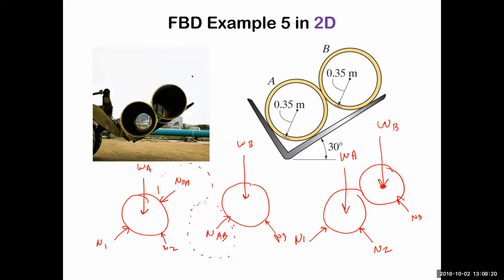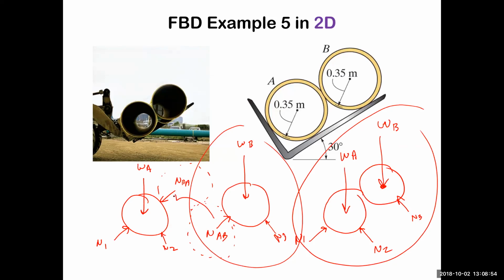So if we're looking at this problem here and we just want to know what these normal forces are, we can take those things. Well, actually, this is kind of interesting. The problem with this one is you've got these parallel forces. Sometimes with a system like this, the way these forces are aligned, you may not be able to solve them when they're together. So we break them apart. When we break them apart, there's only two unknowns on each cylinder, right? There's two unknowns on this one, and then you can take this result and feed it back into this one. So you can do these kind of fancy things.